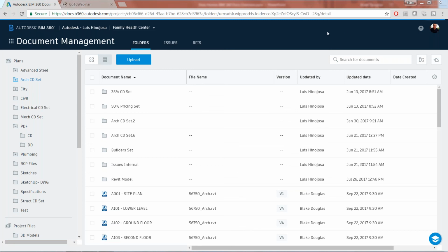When you're uploading, yes. So if they're linked in through Revit already, that's how you can bring them into BIM 360 Docs as a linked file. BIM 360 Docs isn't going to actually create the links for you. The links have to be created in the design tools, and then BIM 360 Docs, by designating them as linked files, simply identifies the support for that.